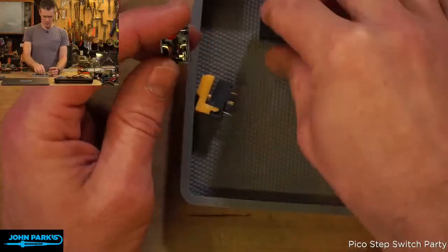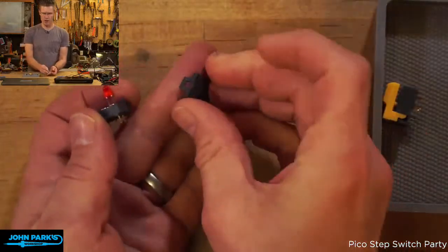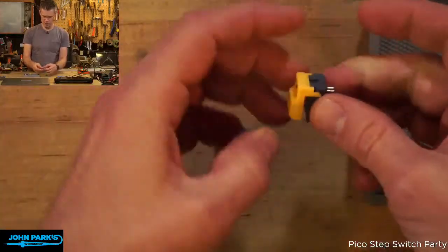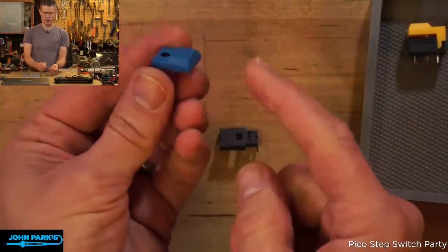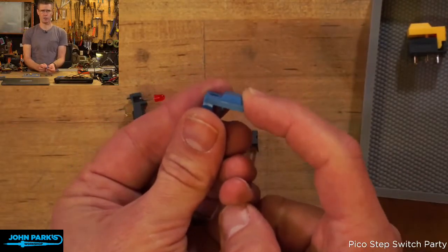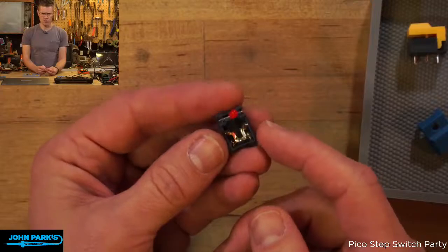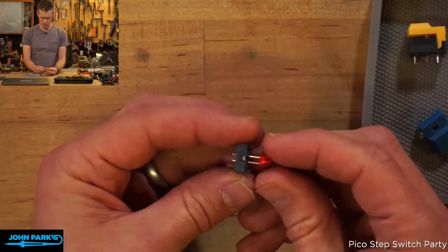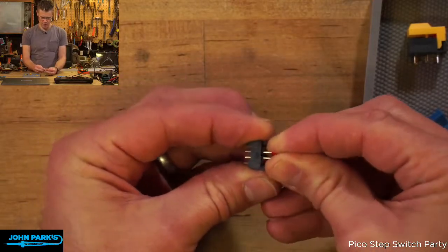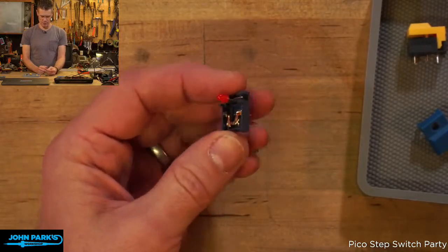So you basically can just pry the thing off. It has a couple little retention clips here on the back and here on the front. Lift those off. You can then pry off the rocker, which is what activates the little switch on the inside, little spring-loaded switch. And then I think I'll take this over to the down shooter so you can see it better. But you can see, first of all, the LED just pulls right out. So long as you keep track of anode and cathode sides of that, you can replace the LED if you felt like it. I like the red one, so I'm going to leave them in there.